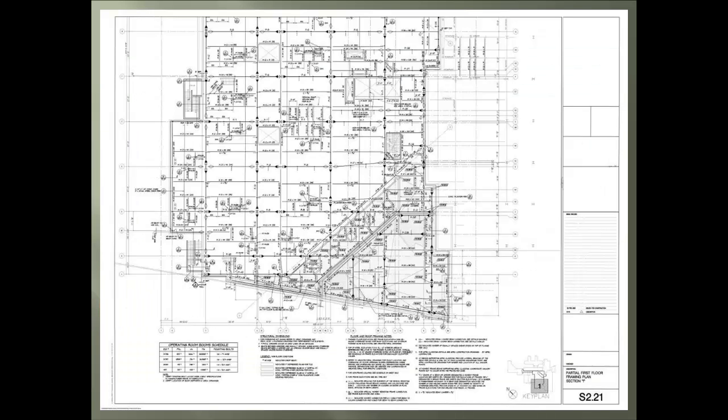Number 14 is for moment frame designations located on the plan view sheets. And lastly, this symbol represents the shop induced beam camber. And the last item is the location or segment of the project floor or level.